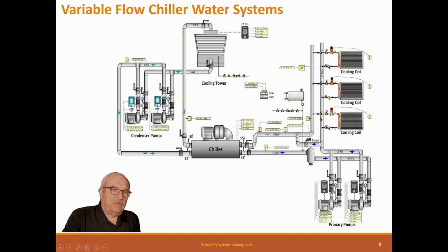And again, these are two-way valves for variable flow. And again, this one might be a three-way, or they may have an automatic valve to bypass them, or even sometimes a 3/4 inch manual valve open between them for that minimum flow.